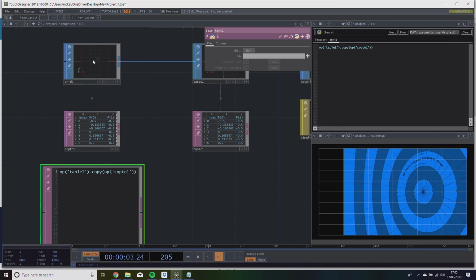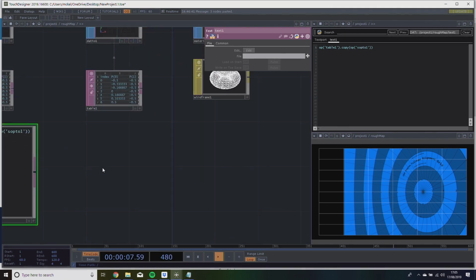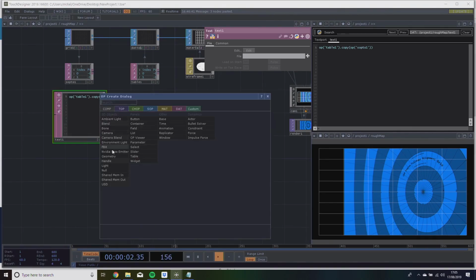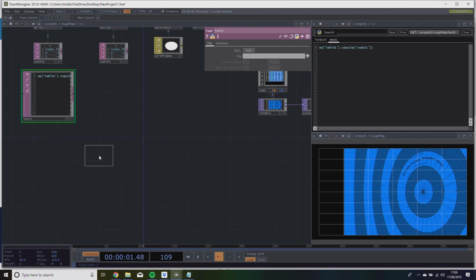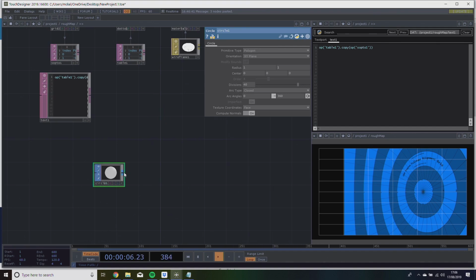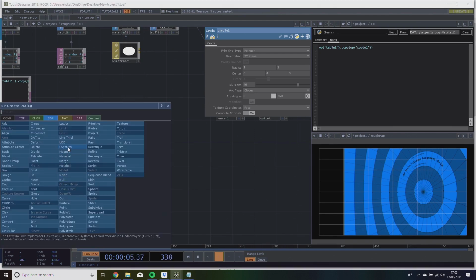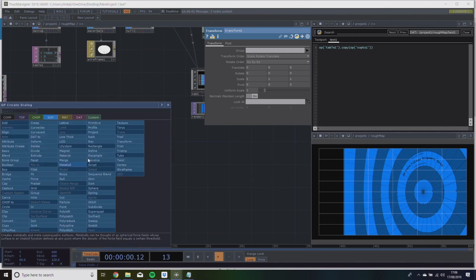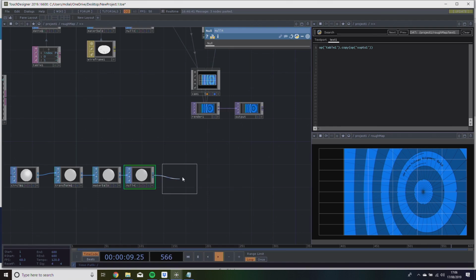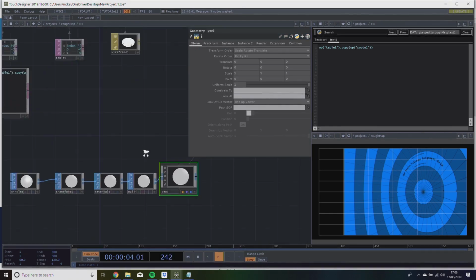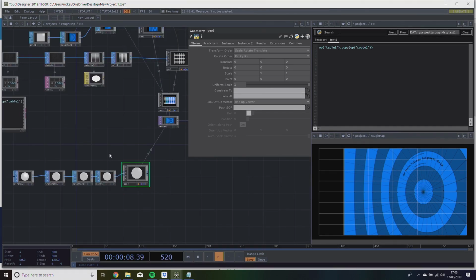What we need to do now is turn all of these data points into physical 3D points. So I'm going to make a new comp geometry. Actually, ignore that. No, I'm not. First, I'm going to make a SOP circle. So we're making a flat, round shape. We are then going to add that to a transform SOP. Then we're going to add a material SOP, null SOP, and then finally right-click geometry. So circle to transform, to material, to null, to geo.